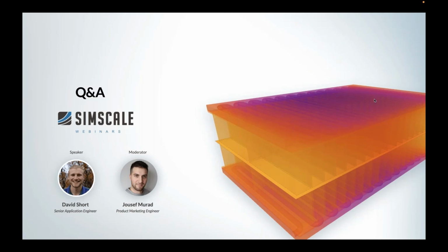In terms of this analysis, because it's a thermo-mechanical analysis, obviously we need to have boundary conditions that are constraining the stress side of things. So we need to make sure we don't have an unconstrained body. We need to fix it somewhere, add some constraint, but we also need to apply those thermal boundary conditions.